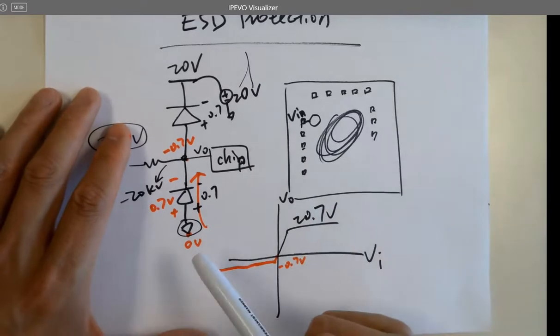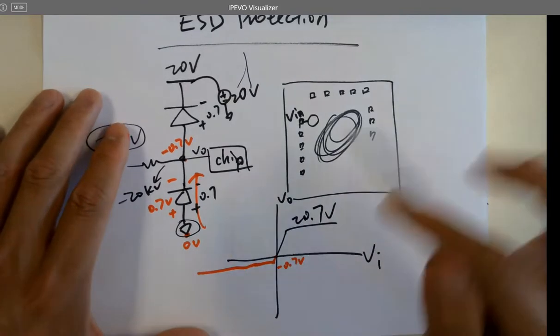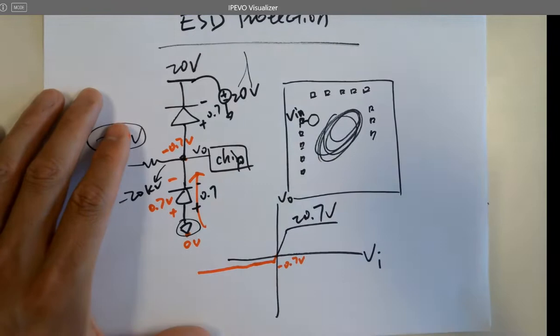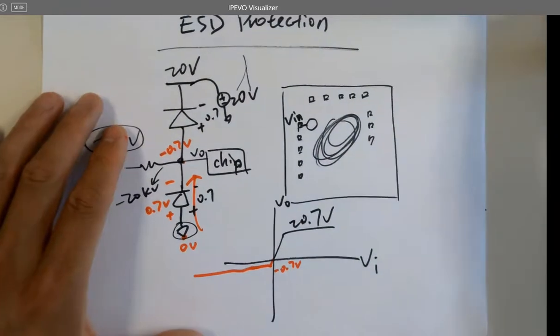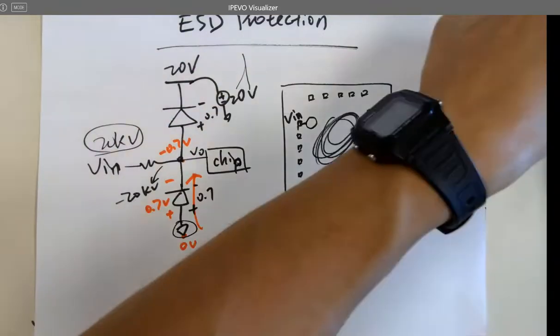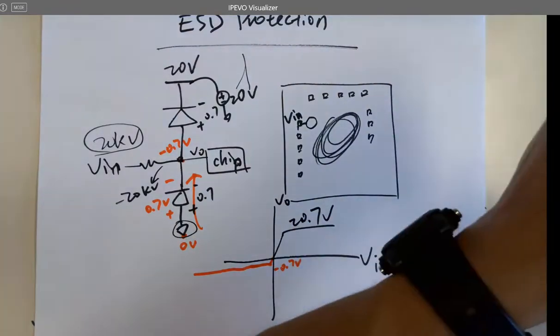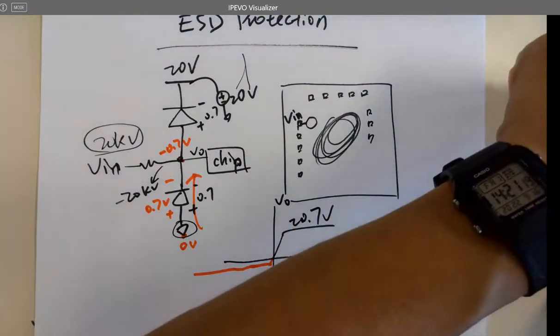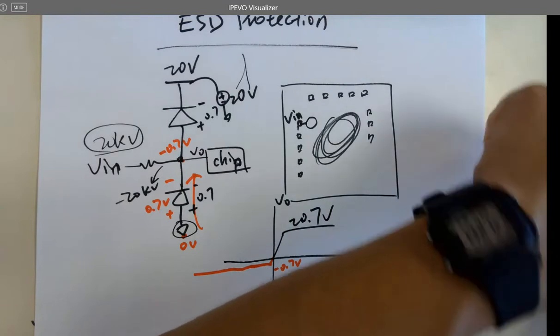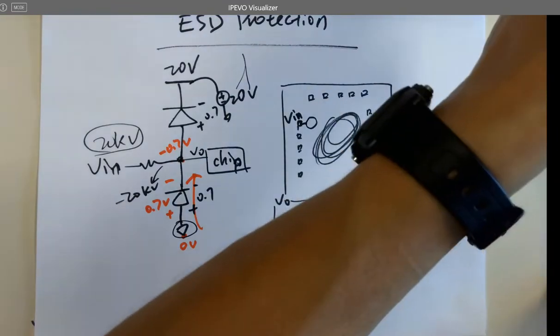For each one. Everything can be touched by our finger, right? Or can be accessed. If you plug into the board, even though it didn't directly touch the pin, there's still something that can be directly shorted to it. If you touch the board and the board got a short circuit to any pins, it's going to damage the whole chip.